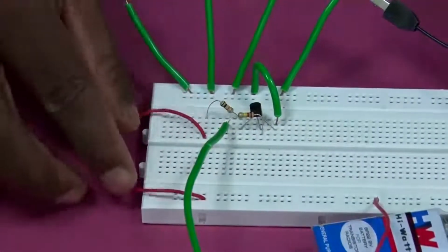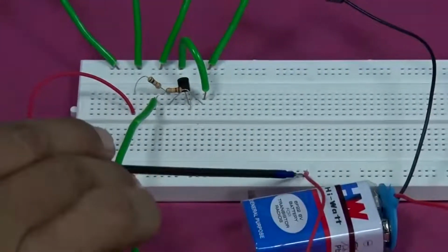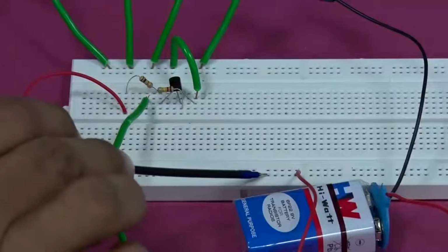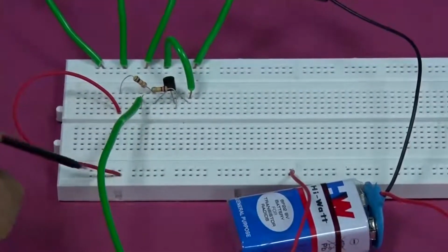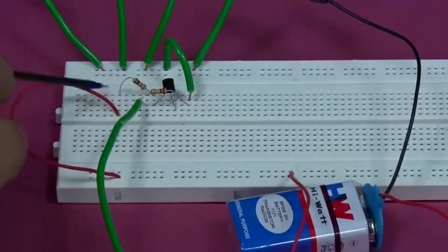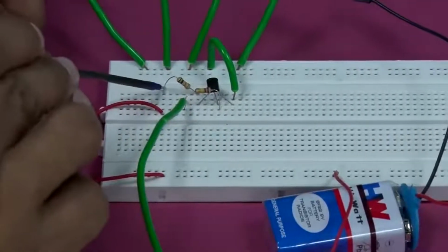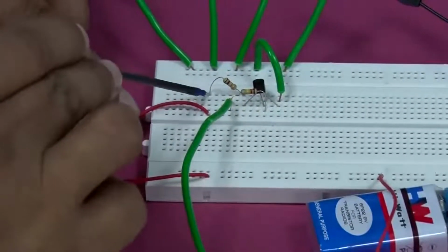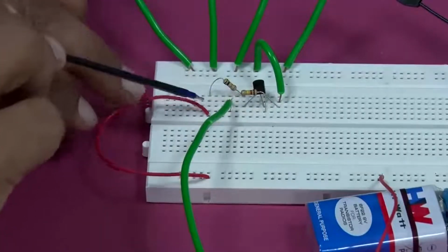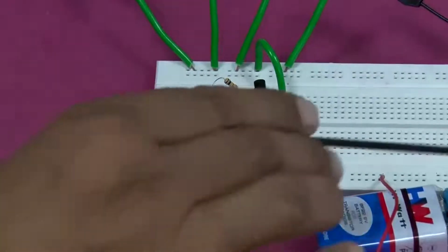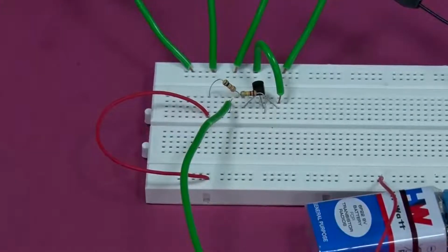Very good. So, you understand the working of the breadboard. This positive of the battery is joined here, but these are all internally connected. So, that 9 volt which is here is also coming here, and from here I am going to this point, and then these ones are internally connected. So, this 9 volt has been connected to this other end of the resistance. One end of the resistor is already connected to the collector. That part is done. The negative of the battery is already at ground. So, our output side is also complete.